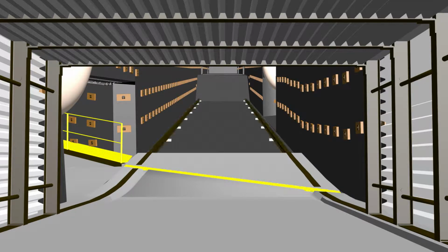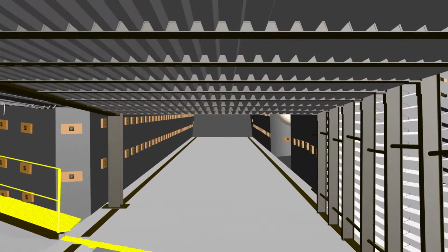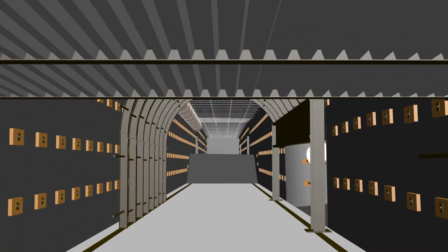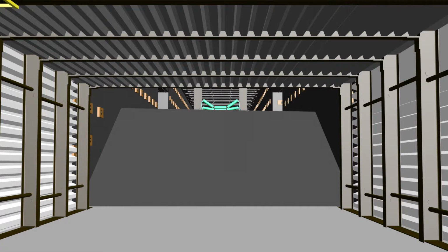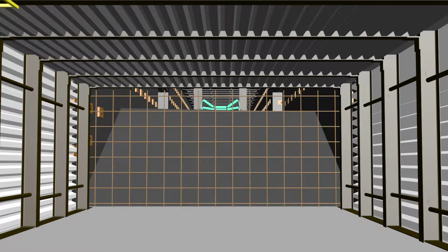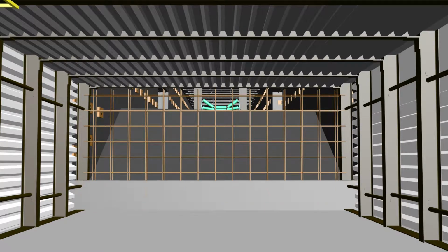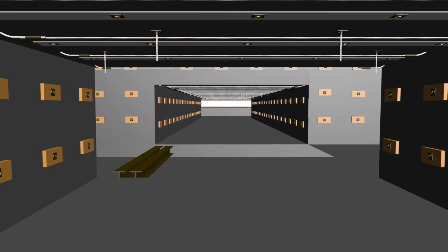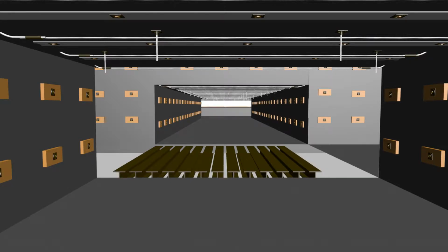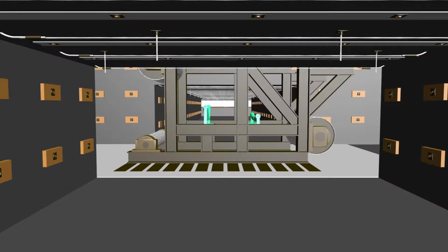The final sill beams are laid down, concrete's poured. First of the king beams goes in, then the second, along with the final arches. At the last arch in the bottom compartment, a concrete wall is constructed. A base is built for the permanent tail of the slope to sit on. And the tail installed.